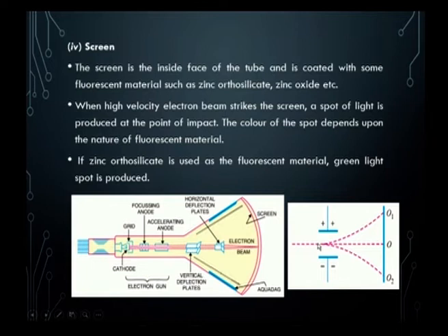If there is zero potential, we can observe the electron beam will have no deflection, that is, the spot that can be observed on the screen will be at the point O. And again, if the polarity is reversed and the potential applied is very low, a decreased level applied to the vertical deflection plate, then we can observe the signal at the position O2.